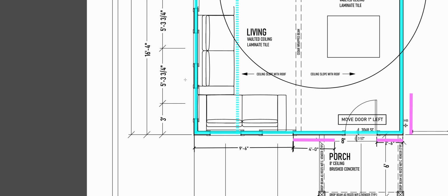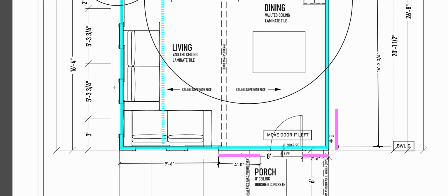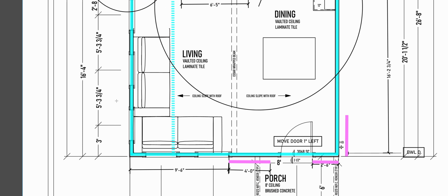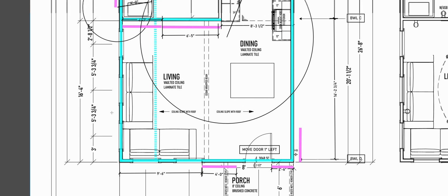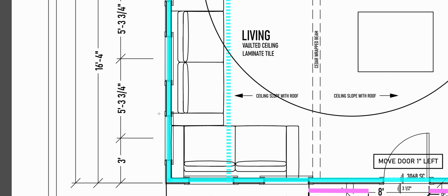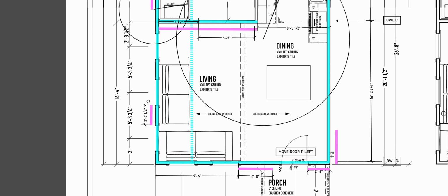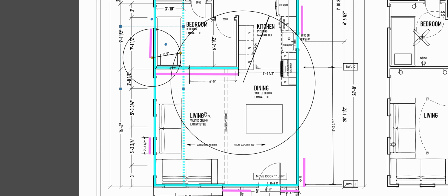This is why it sometimes helps to know as an architect or someone designing the house how to space things out. Because if I cram a bunch of windows and doors into this corner, I can't get any lateral bracing in this corner. And so I'm going to have to do something special. And special means expensive and problematic because if people don't read the plan right and you're not the one doing it, then good luck. All right, so let's just put a panel in there and it'll end up being whatever length it is. Roughly 2'3". And that's within 10 feet of the corner and within 20 feet of the next panel. So get rid of those.